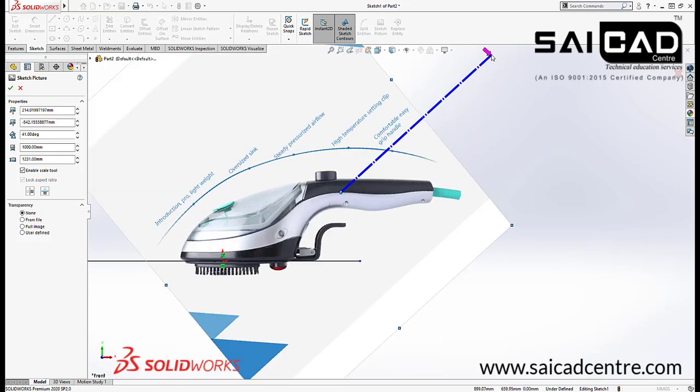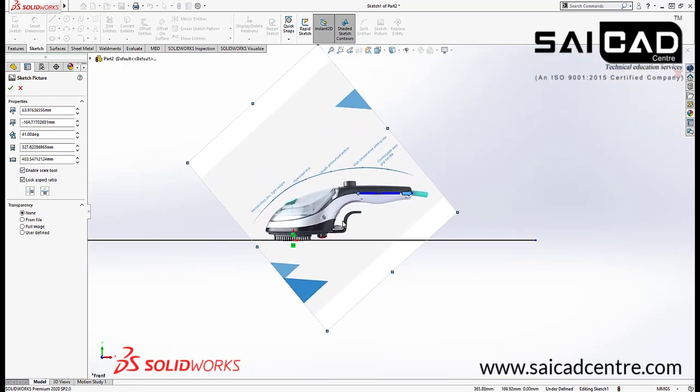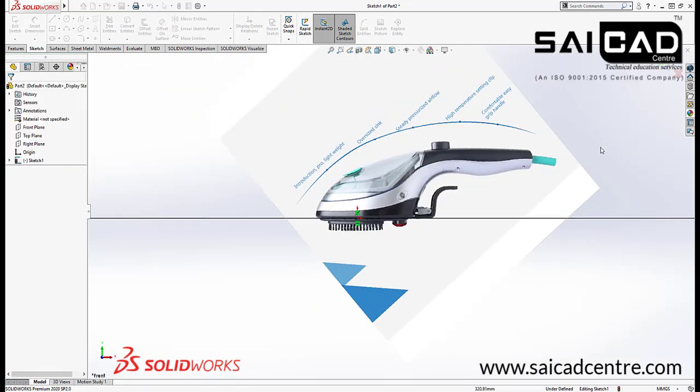So I'm going to select that part from here to here. I'm going to make it around 4 inches with some offset. 4 inches means this will be 25.4 multiplied by 4. So we will get the size. Now I'm going to place it with its bottom face right here. So click OK, and we got the shape.